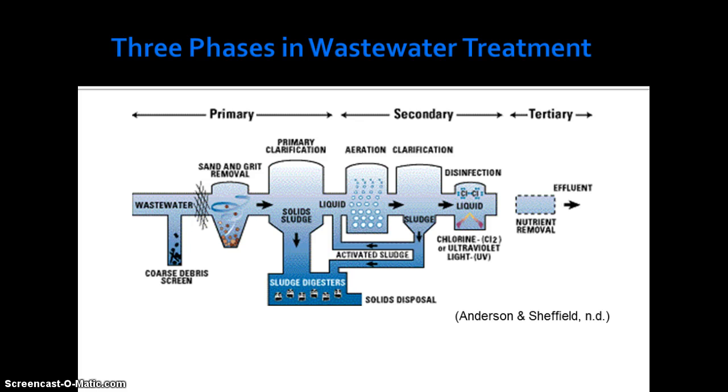Secondary treatment is when the wastewater is aerated, which facilitates aerobic bacteria in consuming organic matter. Recall that aerobic bacteria work more quickly than anaerobic bacteria in breaking down organic materials. Although this process breaks down organics, it leaves dissolved inorganics like nitrate, NO3, and phosphate, PO4. These nutrients are concerning for water discharge as they facilitate biological productivity and eutrophication.